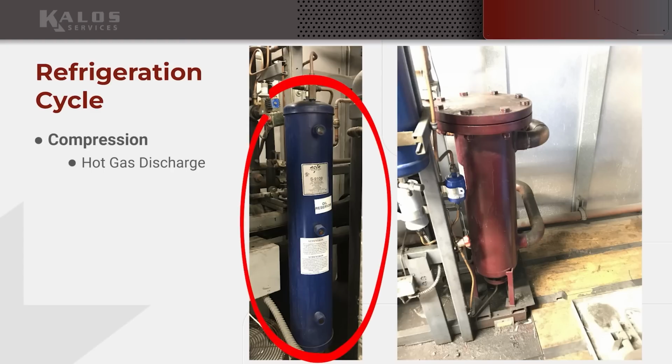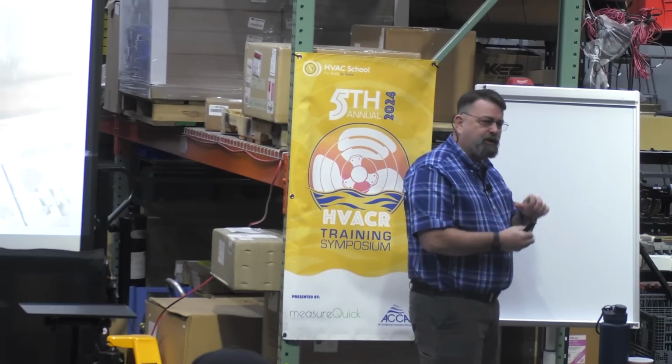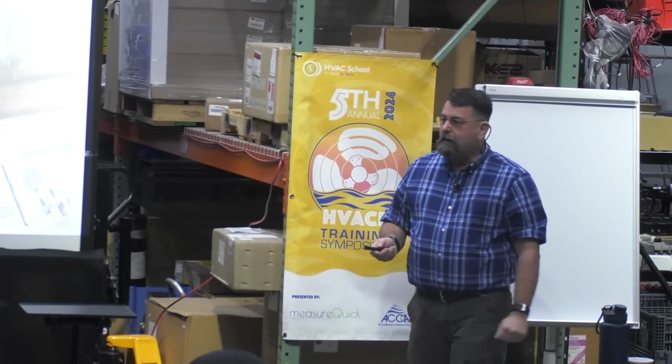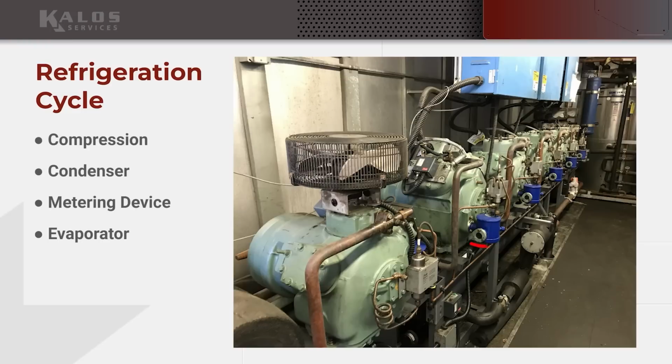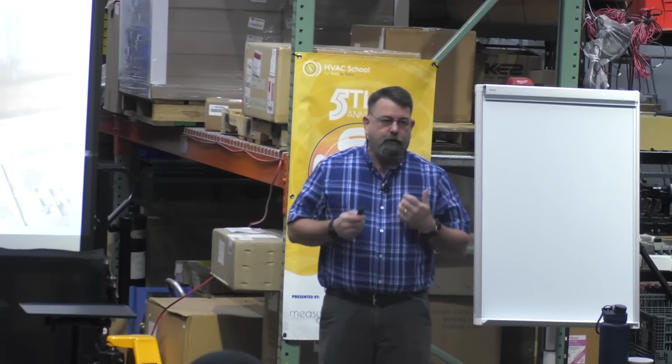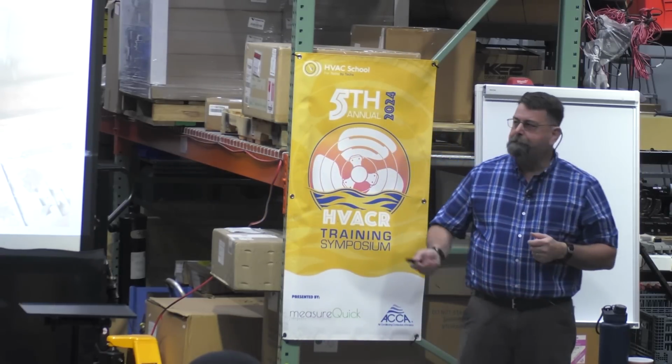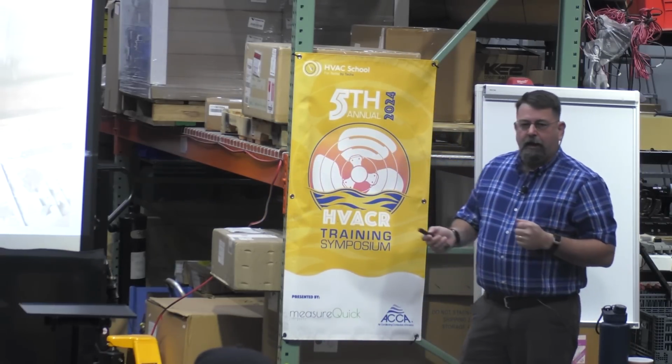Well, that's my oil reservoir. I'm going to have that system over here. It's just going to store that extra oil so when a compressor calls, it gets it, okay? And then that's going to feed the blue thing I showed you on the front of the compressor a minute ago. That's the oil control, and it's going to maintain the right level of oil inside the compressor. So this is a change, right? This is one of the few things that's just really different about it.